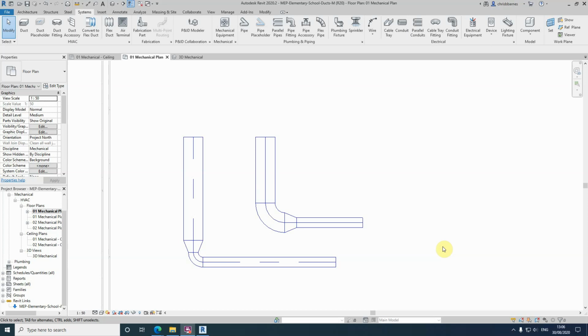In this next video I'm going to talk to you about modifying ducts and pipes. Ducts and pipes can be modified using a variety of standard modifying tools and other specialty tools such as duct pipe sizing, converting placeholders, changing rigid ducts and pipes to flexible ones, adding insulation and lining, and modifying the justification of ducts and pipes.